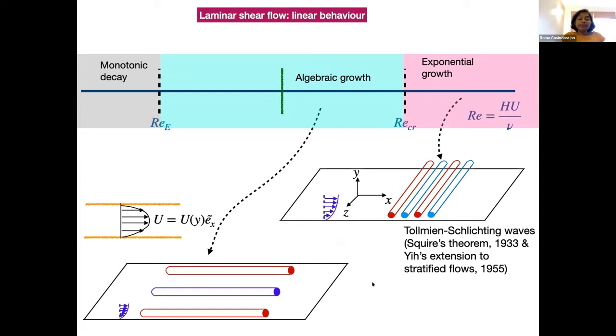There's a question. What does the critical Reynolds number depend on? It depends on the flow geometry primarily and the flow setup. In a straight channel, that number is always 5772. For a boundary layer under low free stream turbulence, that number is always close to 200. But if you change it slightly, you make it divergent or convergent, it will be very different. For a jet, for example, it's 5 or 10 or something like that. So it depends primarily on the geometry, the boundary conditions, and the way the flow is. Is it pressure driven? Is it flowing due to a boundary movement?